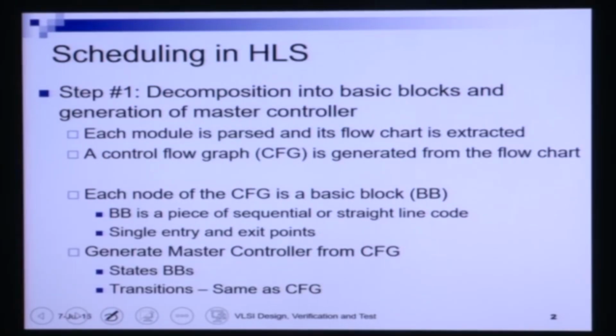How have we come to this place? So, firstly we said that the application will be defined in terms of a high level hardware description language like Verilog, describing its behavior. Now, after we have obtained this Verilog code, each module of this Verilog code will be parsed and the flow chart from this module will be extracted. Now, corresponding to this flow chart, we will be able to obtain a control flow graph of the module.